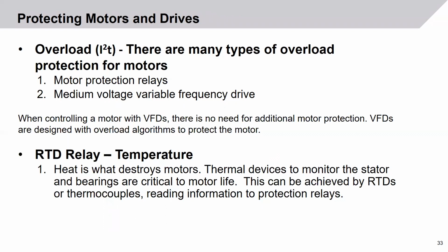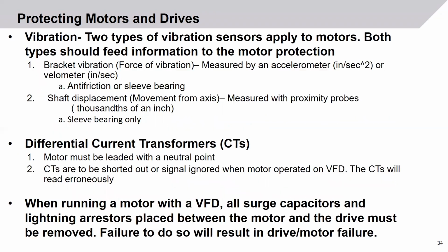RTD relays, heat is what destroys motors. Thermal devices to monitor the stator and bearings are critical to motor life. This can be achieved by RTDs or thermocouples reading information to protection relays. There's also another protection for the vibration. Now there's two types of vibration sensors that apply to motors. Both types should feed information to motor protection.